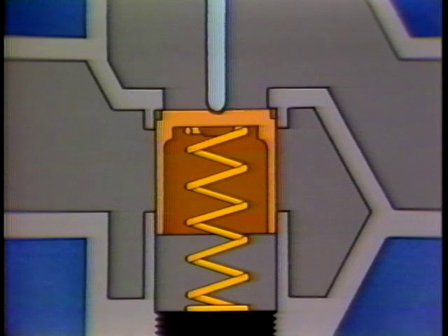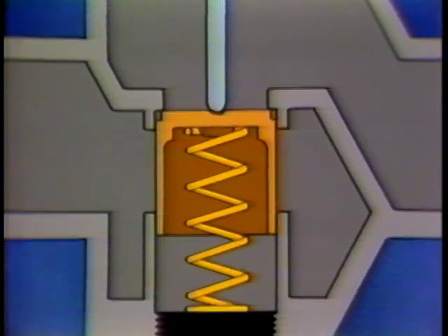Even very small dirt particles could keep this valve from moving. The solution is a loose-fitting piston supplied with a sealing ring, just as in an automobile engine. This piston ring also scrubs the cylinder wall as it moves, preventing dirt buildup. A special advantage of the pilot-operated PRV is that the long stroke of the main valve allows the use of